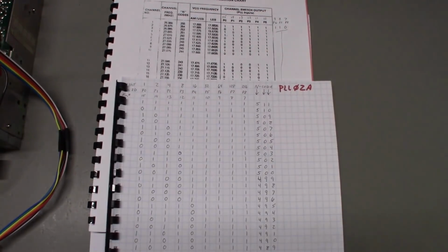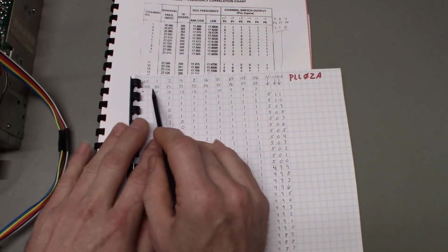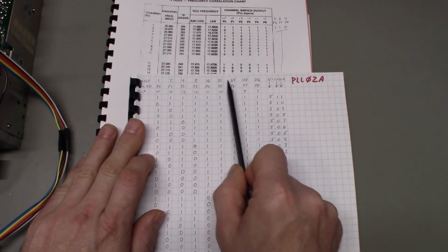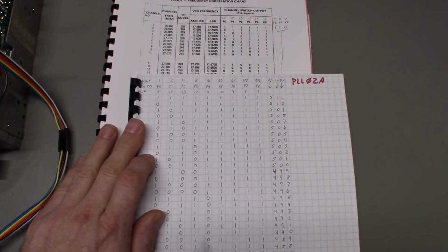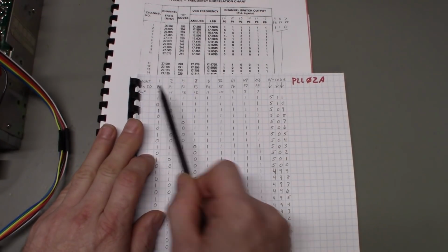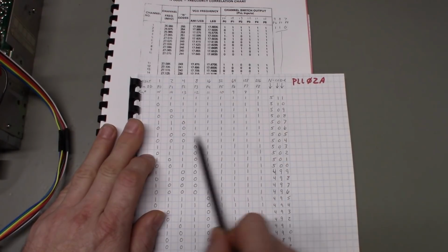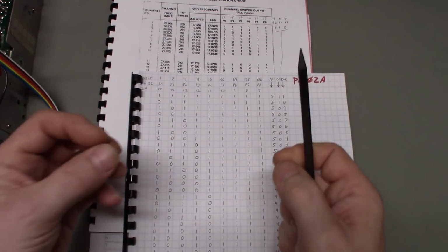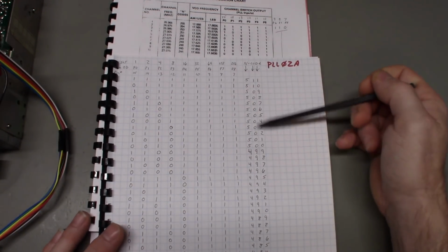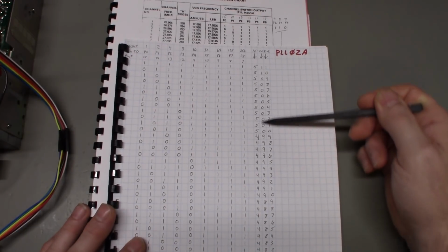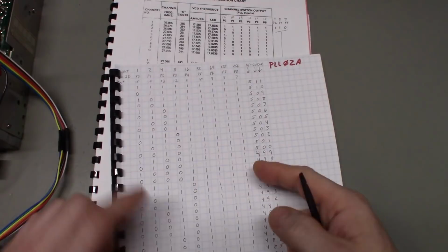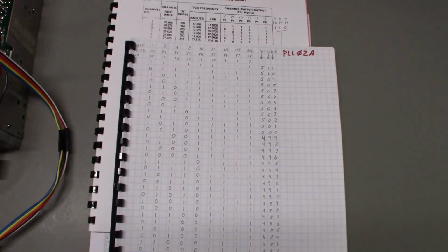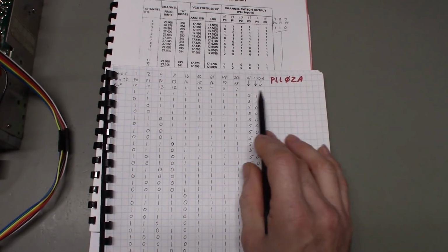All the manufacturers. Now, what I have written here, across the top, I have the weight for each of the pins. So you can see 1, 2, 4, 8, 16, 32, 64, 128, 256. I have the pin ID, so P0 through P8. I also have the physical pin number, so pin 15 through pin 7. That's the actual physical pin on the IC. I have the decimal number, or the N code, written over here on the right, and then the binary number for every possible channel, or every possible N code, is written over here in binary. And you can see I started at 511.